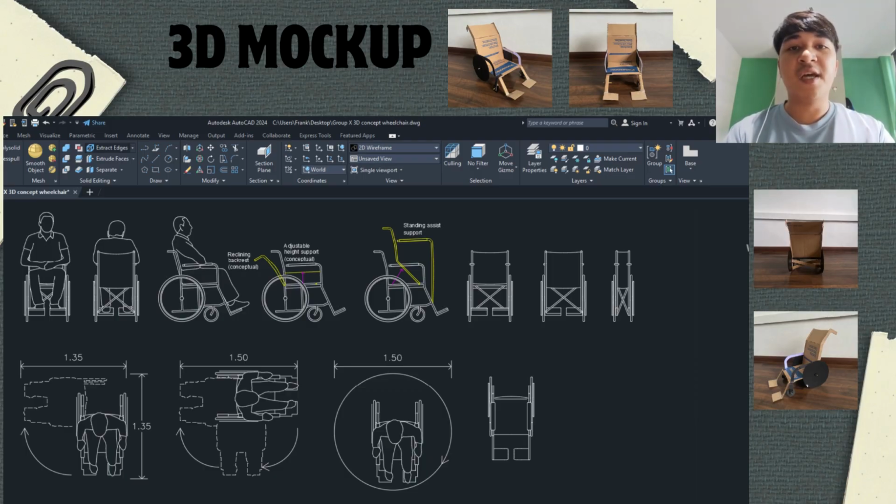The second modification is the adjustable height support, which is also indicated conceptually beneath the seat area. This mechanism allows the seat height to be raised or lowered to suit different user needs, such as transfers or interaction with surrounding surfaces. In the drawing, the height adjustment is shown schematically to emphasize functionality rather than mechanical detail. This feature is important because changes in seat height directly influence the wheelchair's center of gravity.